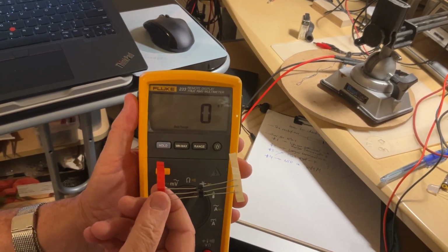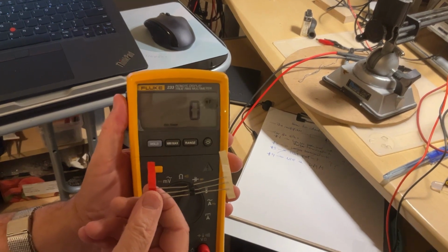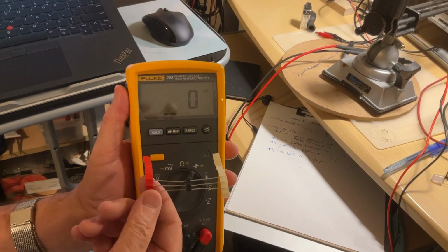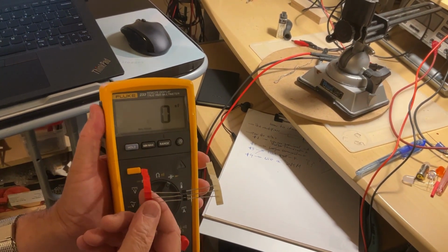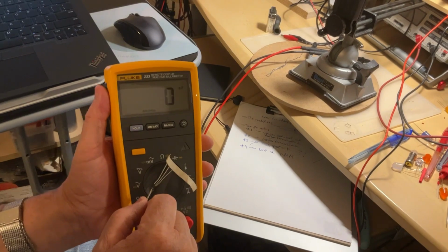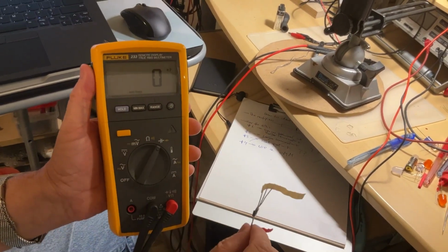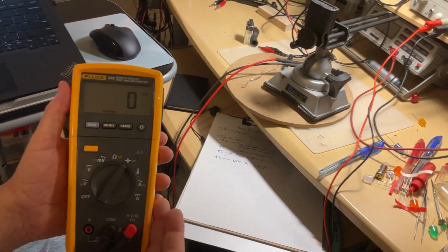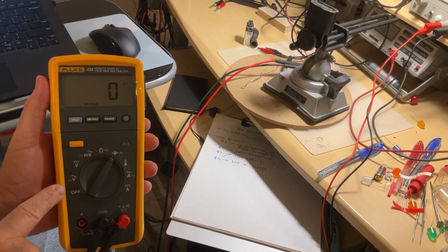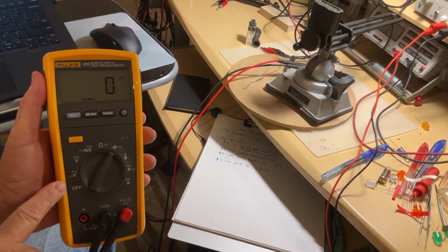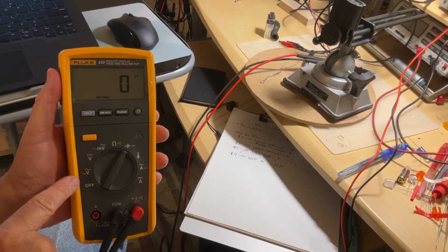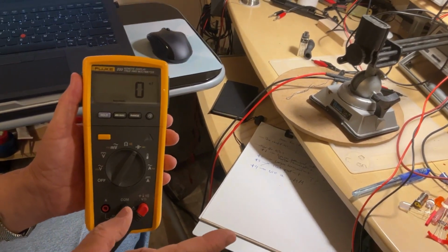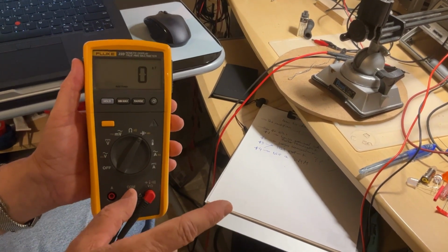And any rectifier you measure with any meter, it doesn't matter how cheap it is. You can even find meters on the market which are $10. All of them are measuring very nicely the rectifiers. But that position of the diode on the multimeter, it's not designed for LEDs. So what happens is there are some multimeters having the power supply inside 3 volts. With these ones, you almost never be able to find the diode conducting or not conducting, and I'm talking about the LEDs. Only about the rectifiers, but not the LEDs.